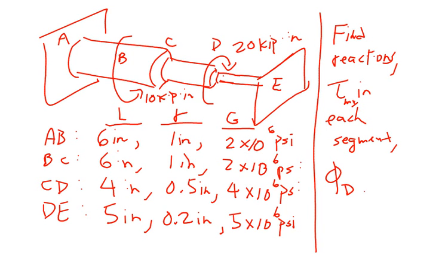So in order to look at the applied loads, you have to remove one of the supports, because the applied loads want to deform the shaft in some way, right? And what having both supports does is it prevents that. So in order to look at the full effect of what the applied torques are going to have, you have to remove one of the supports so that this shaft is allowed to deform freely based on the applied loads, okay?